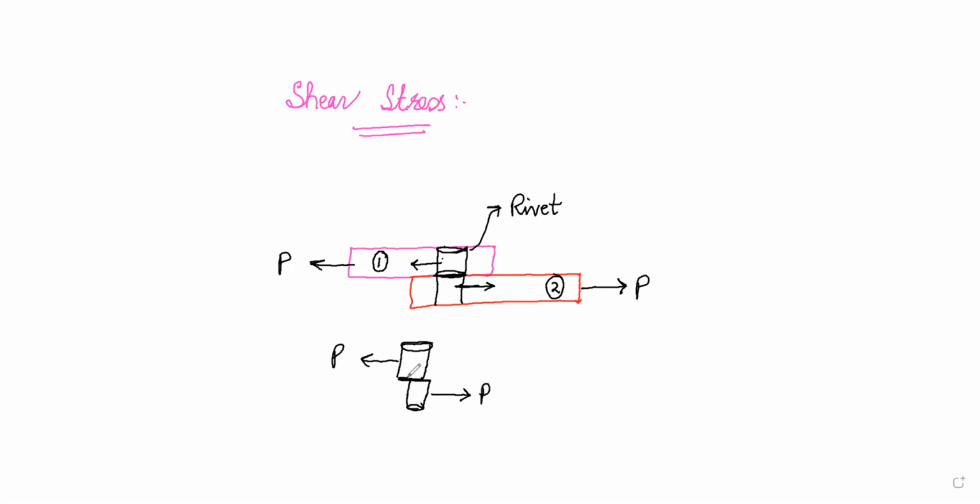So if you look here, this surface out here will try to resist the deformation created by this load. Now say for example, these two portions are in equilibrium, they are not moving at all. So if you separate the lower portion or the upper portion, we can draw the free body diagram for the lower portion.